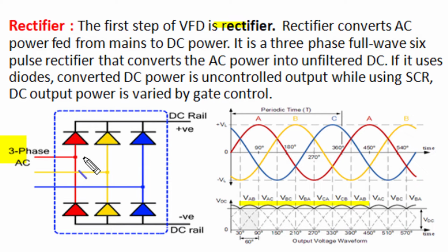So this uncontrolled diode three-phase full wave bridge rectifier produces a constant DC magnitude with a certain amount of ripples as its output. Now we can control the DC output of a rectifier even when we have a fixed three-phase AC voltage applied at input. But for that, in place of a simple diode switch, we have to use an SCR as the switching device, and this three-phase full wave fully controlled SCR bridge rectifier circuit can produce a variable DC output here.